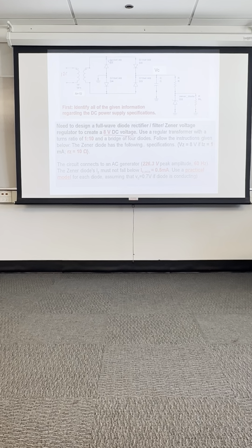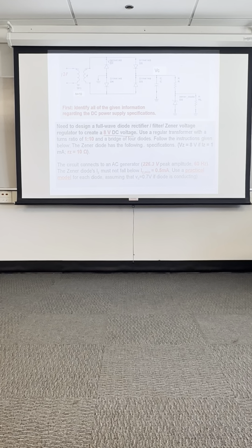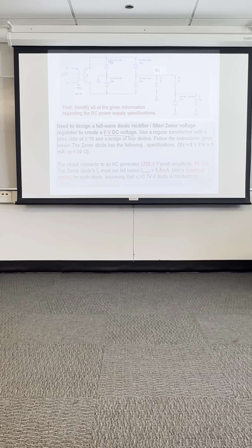What's the voltage on the secondary? It's a 1 to 10, inversely, divided by 10. It's not actually dividing. When you get into transformers, you get into the electromagnetic theory of how these work. They're actually coils of wire. So it will divide the 120 down to about 12 volts.